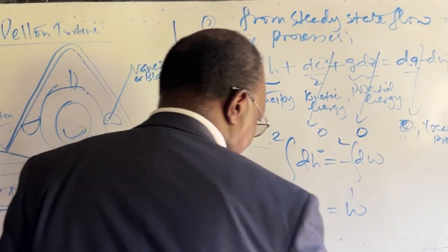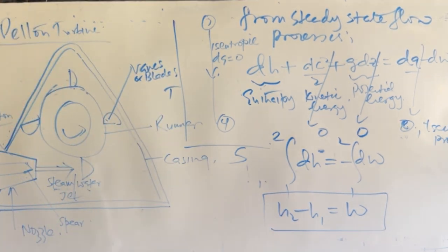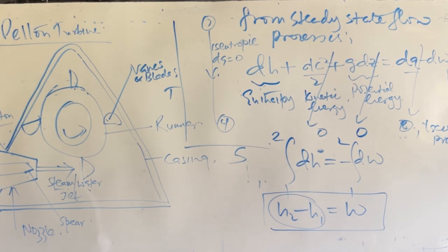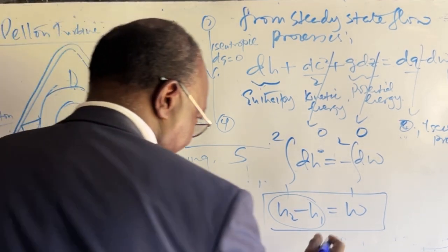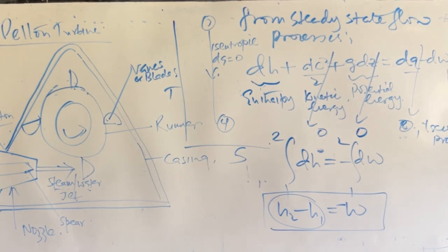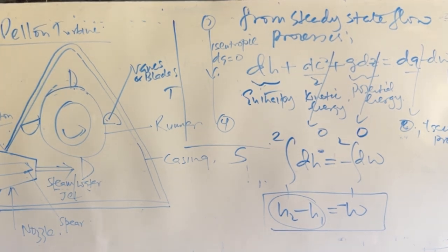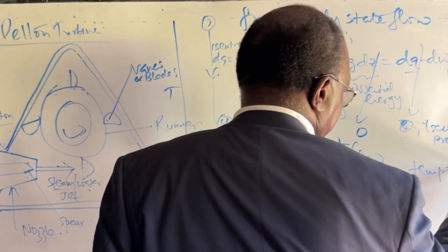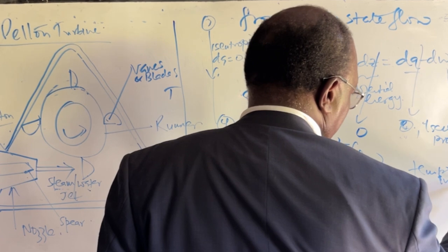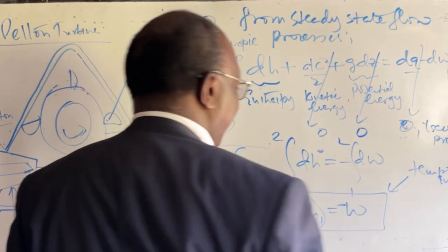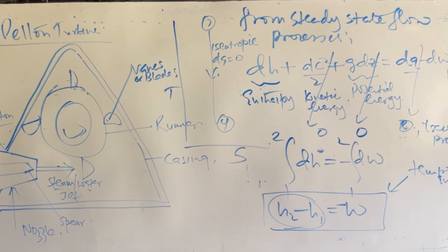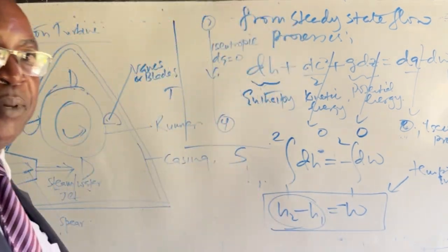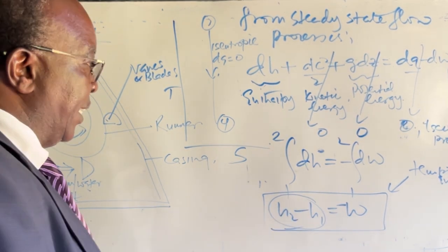So, what does it mean? It means that the work output from the turbine depends on the difference in the enthalpies at the exit and the entrance. Very important. And this will be determined significantly by the temperatures in the boiler. Because remember, H, all said and done, is heat transfer under constant pressure, and heat has to do with the boiler. So that's a mnemonic for remembering what really affects this.